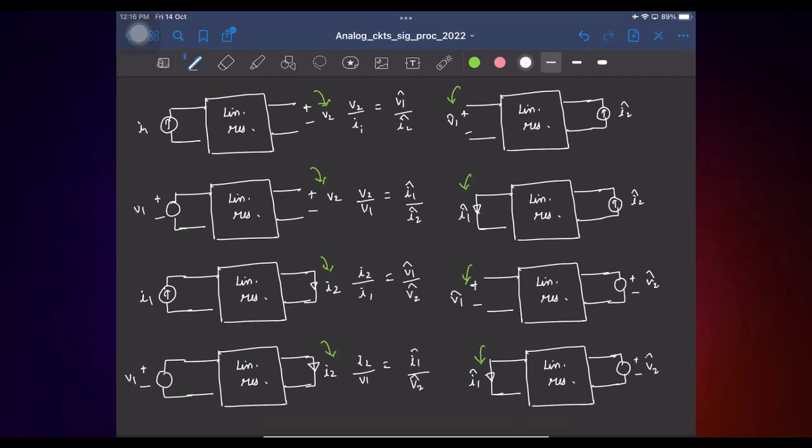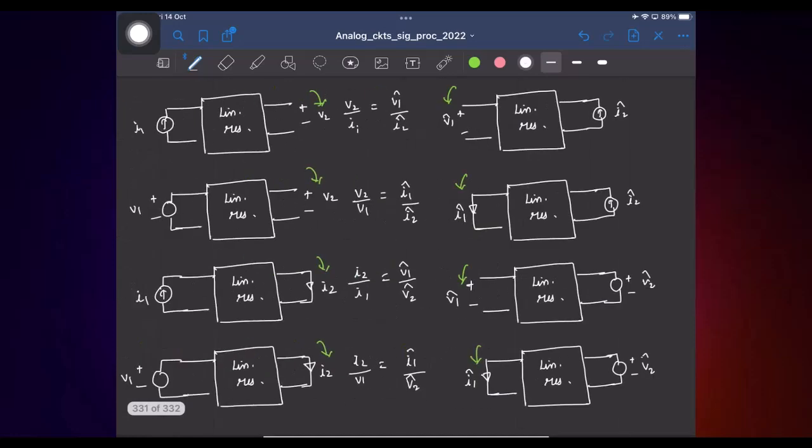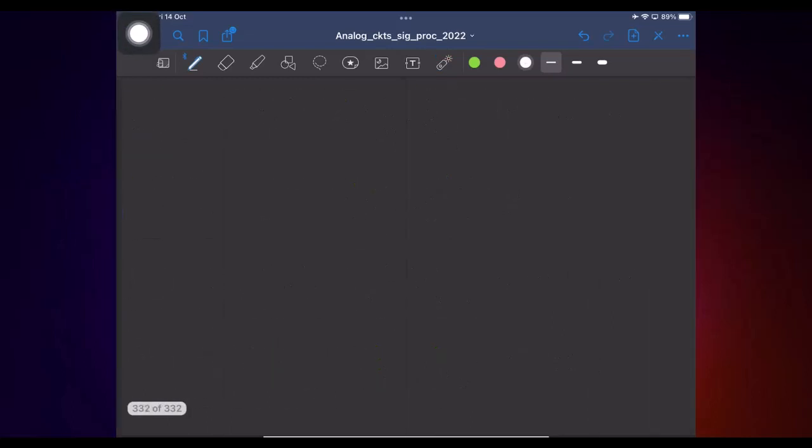Okay, cool. And this is again valid only if we can cancel the summation Vk Ik hat and Vk hat Ik for the internal branches here, right? And for the example we have chosen, that is happening because the branch current is proportional to the corresponding branch voltage, right? So this is good, but we just have considered a network which contains only resistors, so this is still boring. So to make it interesting, let's say we consider a network containing capacitors and inductors as well. So now this is a network containing linear RLC.